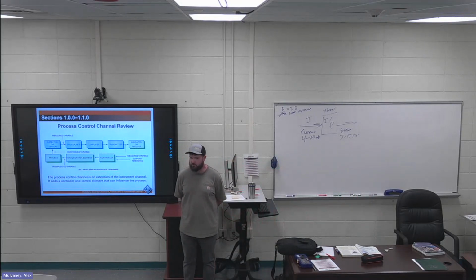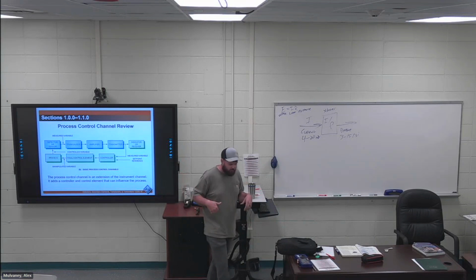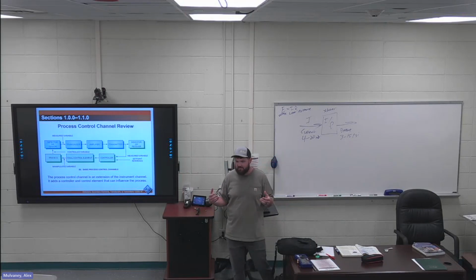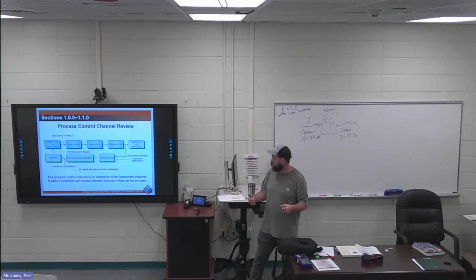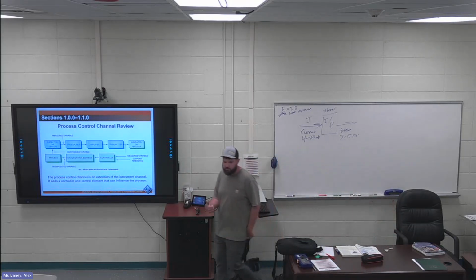Everybody knows what an orifice plate is. You've probably heard the word orifice plate 6,000 times. Pressure comes to an orifice plate, hits it, creates pressure, right? Backside, there's less pressure, and the differential pressure gauge is taking the two pressures and determining a flow or a level, right? But that pressure is hitting that and creating a head loss. That is loading. You are creating a disturbance with a known effect to tell what the flow or level is. That's what loading is. It's taking energy out of the system in order to tell a temperature.